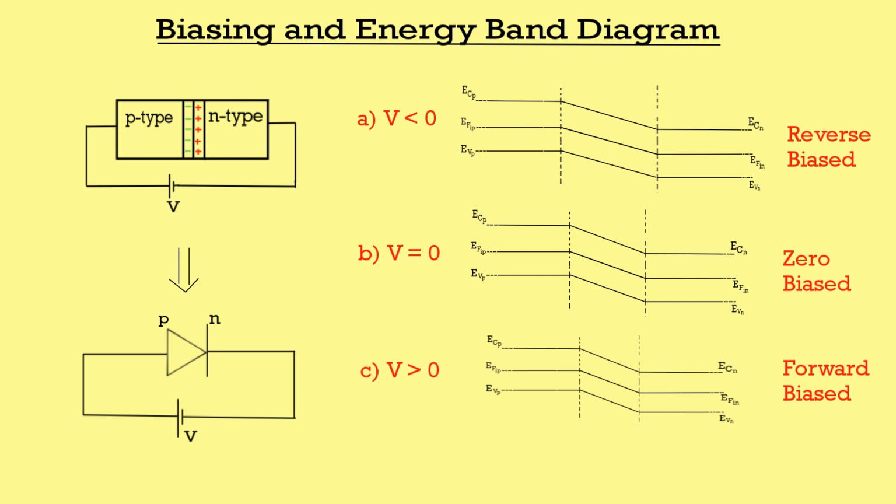It is quite interesting that in forward biasing, the battery voltage actually opposes the built-in potential, and as forward bias voltage is increased, depletion layer width reduces as energy bands on the N side are raised. When the forward bias voltage is equal to the built-in potential, the depletion layer completely vanishes as the energy bands get aligned and the majority carriers can cross the junction.